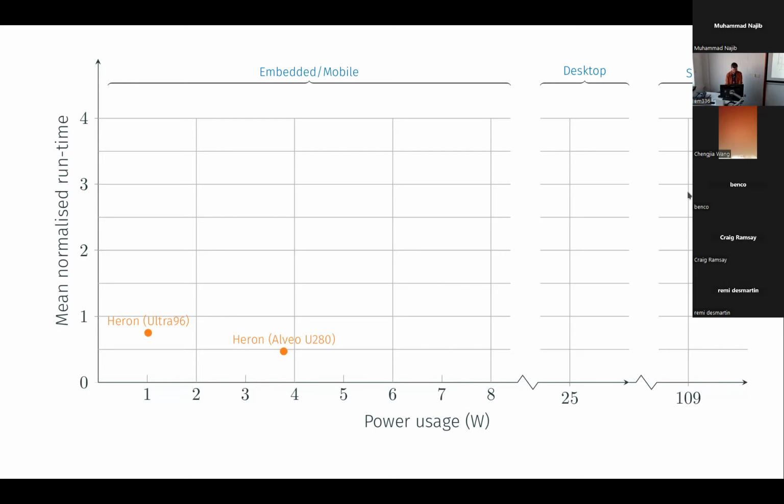So this Alveo one, that is the board we would like to use for our big multi-core system for the end of the project. So that's the one we can fit 50 cores on. Meaning almost all of it is unused, but we're still committing to that power budget of keeping the whole device alive, right? So the power consumption of this is going to be very pessimistic.